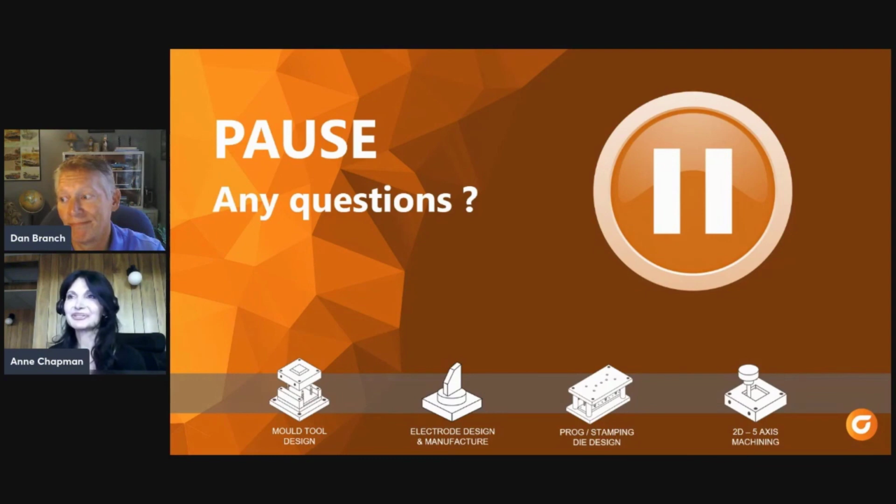Okay. Madison Jones says, very cool. Can you export BOMs to SolidWorks, or can you create drawings in Cimatron? Cimatron is full CAD and CAM, and that includes a wonderful drafting area. So yes, you can make drawings that are fully detailed. In fact, you can automate drawings because we use a templating system. I don't want to say push button, but very easily you can get mold layout drawings. You can add your bill of materials, balloons, all the stuff that you would expect. As far as exporting the BOM, it exports to an Excel doc or different types of formats, like I was saying. So as long as SolidWorks can read one of those formats, it can go in there too.